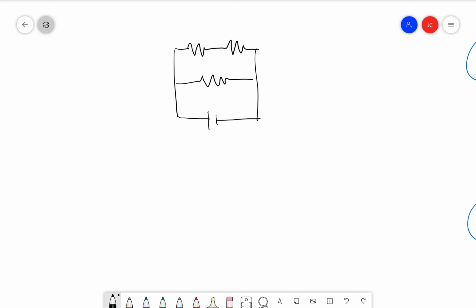So this time, we're given some limited information, and again, it's all about what information you're given that always matters. So I'm going to number these resistors. Here's R1, R2, and R3. R2 is 3200 ohms. R3, we don't know. We know R1 is 3800 ohms. Then we're given the total current, IT, 58 milliamps. And we're given the voltage on R1, 120 volts.